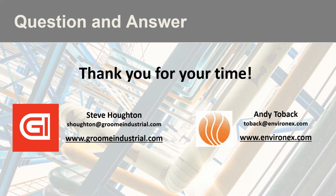Let's see. So I've done lots of versions of this over the years. It's a great question because you're definitely changing the bulk flow of the catalyst when you're fogging and especially with removing water injection. You'd want to traverse both and come up with a tune that would probably make them both happy, because trying to adjust the valves daily is problematic. You'll never get exactly where we had left it during the tuning exercise. You'll never get that back. So once you find the sweet spot in a tune, you want to not touch those again.